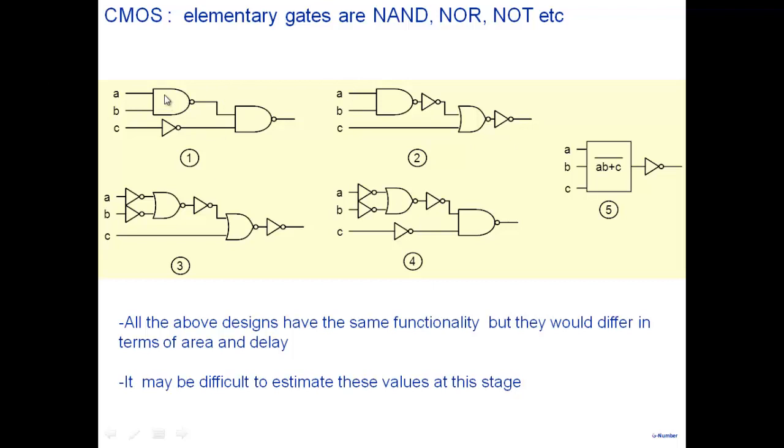If I have a delay of a gate available to me, NAND gate delay is 2 nanoseconds. Or 2 picoseconds, or whatever, 2 nanoseconds, let's say. This is also 2 nanoseconds. Inverter delay is 1 nanosecond. What is the worst case delay? 2 plus 2, 4, right? You think that's the correct estimate of delay? 4 nanoseconds?